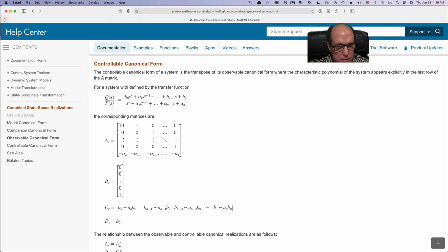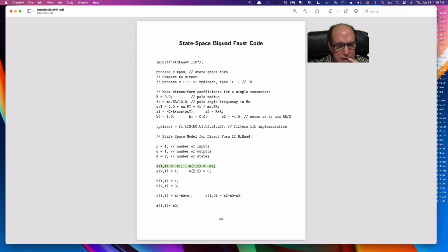So we found it on the top row. So what we had was a controllable canonical form with a permutation. It's just like renumbering the states oppositely. So to just flip this up down, you would just renumber the states in the opposite order. So here we are just entering those numbers, and you can see that we are controllability canonical because we're feeding into one state. Can't introduce zeros that way, but the output could have a zero, so it's not necessarily observable.